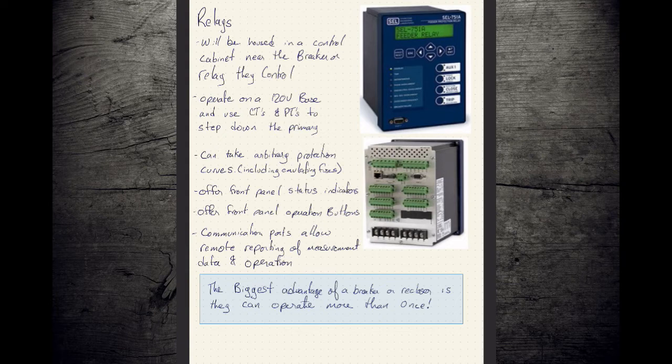And then you've got some communication ports. This particular one, that's a fiber port. You've got Ethernet, you've got serial, that's serial 485 usually. You'll have your CTs and your PTs coming in, and then these guys here are available for extra I/O points for different things you might want to monitor or measure or control.